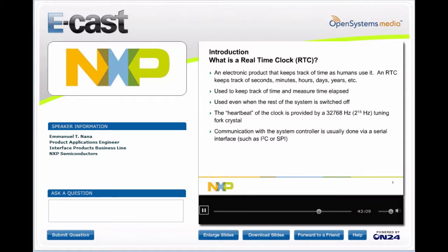And there was a similar question regarding the PCF2123, asking why it has an output enable if the output is open drain. The reason is that with the clock output, even though it has an open drain output, if the clock output is toggling, it still consumes some power.